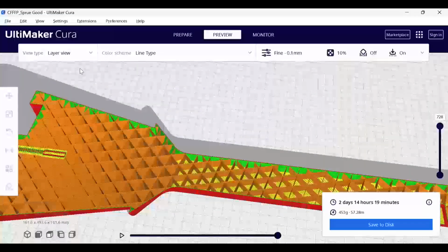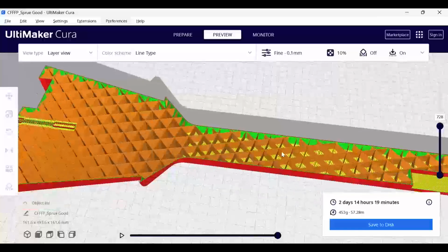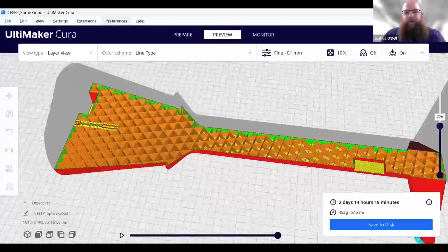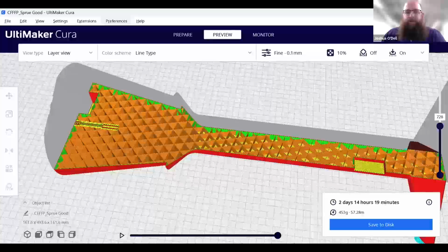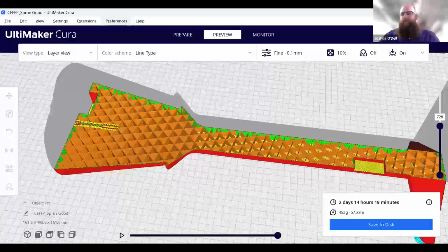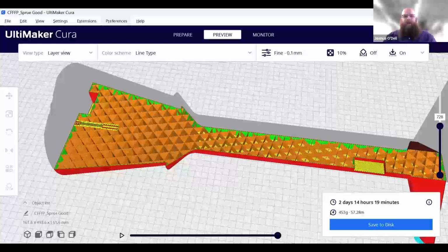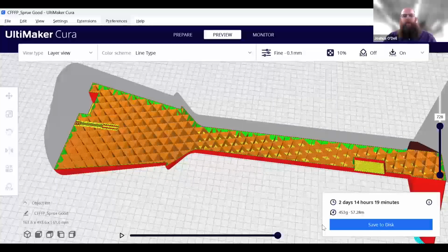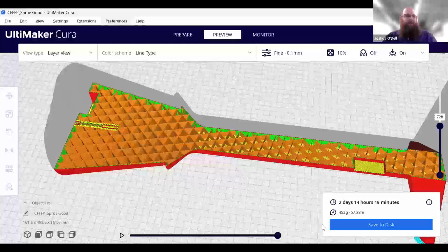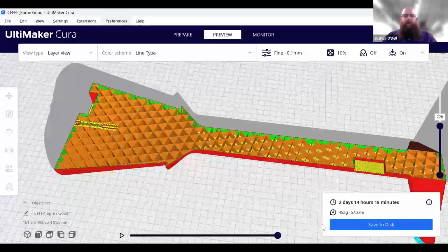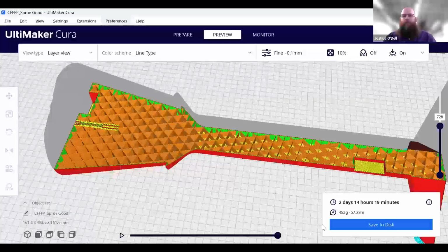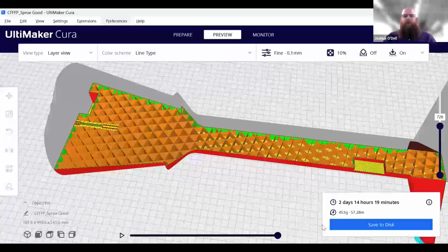How do you make your trees if you don't print them? Our investment casting trees, we pretty much exclusively use PMMA printed trees. We've talked about getting like an injection tool for it, but a lot of times we change our trees pretty often to incorporate different sensors and things like that. So we'd have to do a lot of tool modifications along the way. And frankly, we don't really print for production. Most of our prints are for research, so we're not using nearly as many trees as a typical working foundry would.